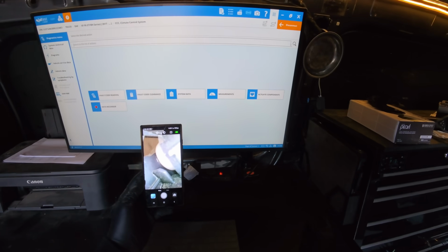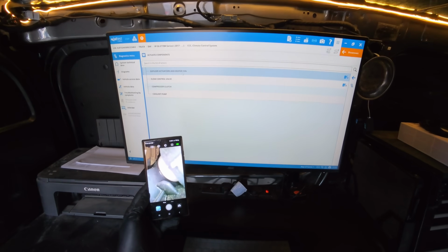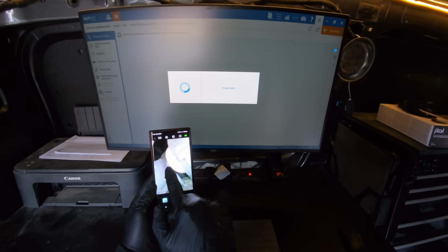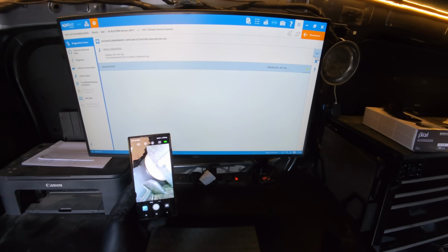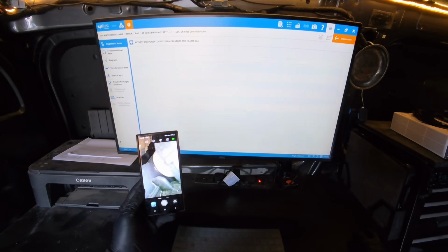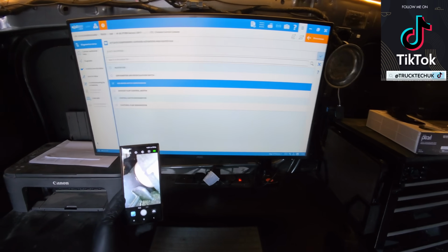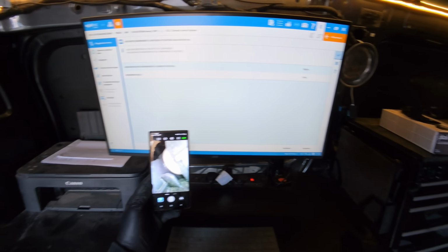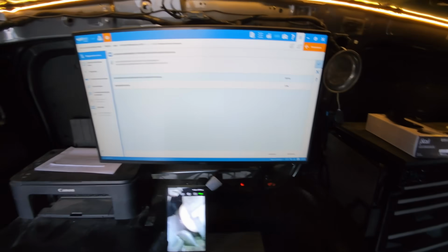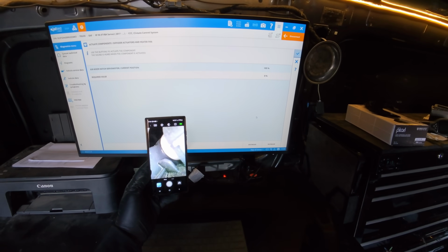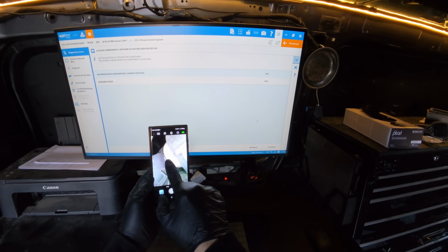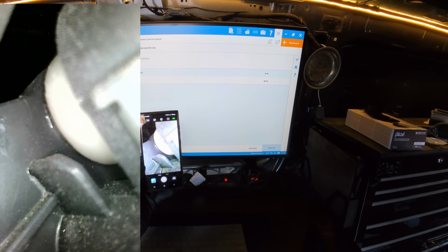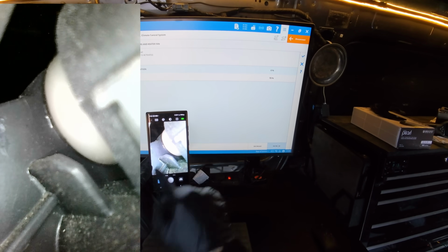So what we'll do now is we'll go to Actuate Components, Diffuser, Actuators and Heater Fan. And we'll watch this spindle, hopefully it'll be in focus enough, and we'll go to the air mix flap and check that that's moving. So this is the air mix hatch servo motor that we're going to move. And what we can do with this test is increase its value. You can already see it's reset back to 0, but we'll watch this now and increase it to 100% and see what happens. You can see it's moving on here.